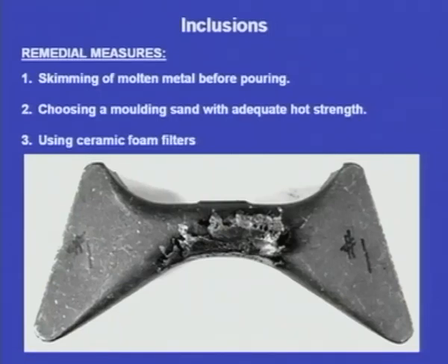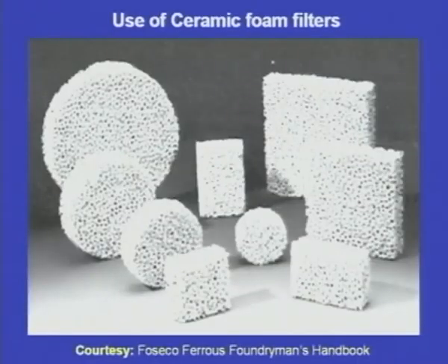And next one, using ceramic foam filters. By using ceramic foam filters, we can filter this foreign material. So these are the typical appearances of the ceramic foam filters. They are available in different shapes and different sizes. These ceramic foam filters are to be inserted inside the gating system